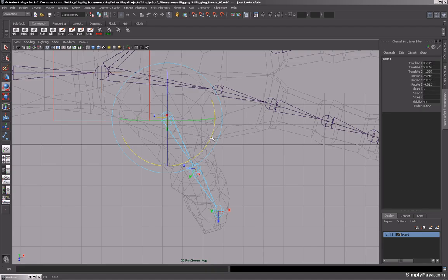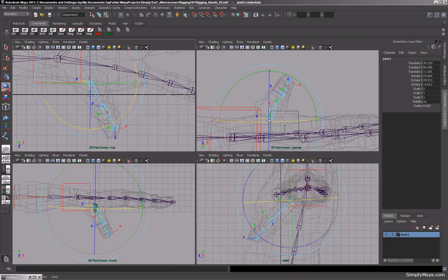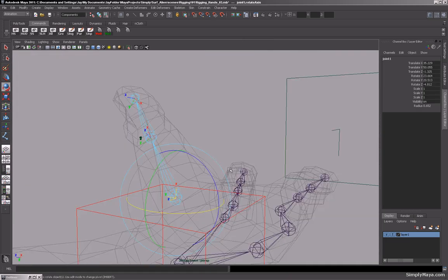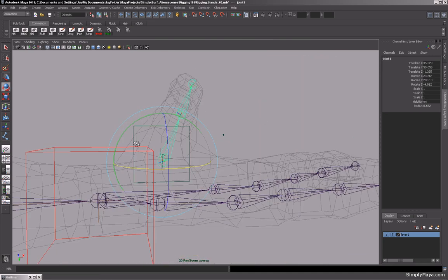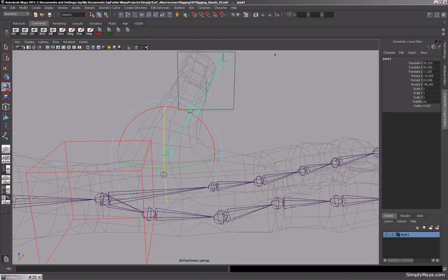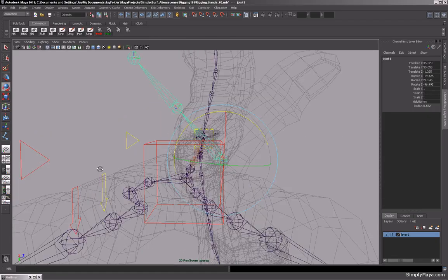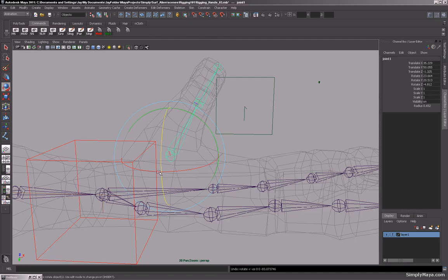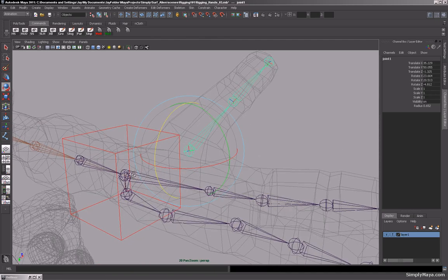So that's going to be the rotational axis for that part of the thumb itself. So now if I hit F8 and go back, you can see now that the rotate tool will all bend accordingly like that. So that's now actually kind of correct. Okay, so it's just one of those things to be aware of.